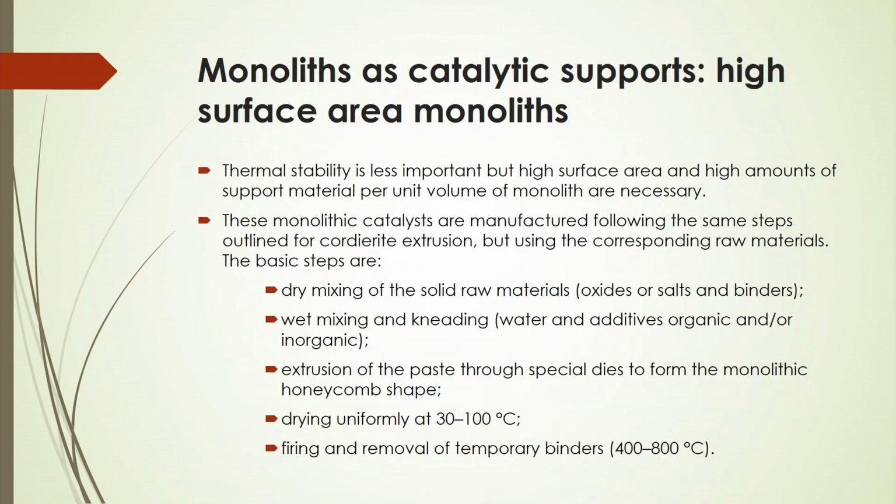And for high surface area, you will get some other characteristics. In that case, thermal stability is less important, but high surface area and high amounts of support material per unit volume of monolith will be necessary.